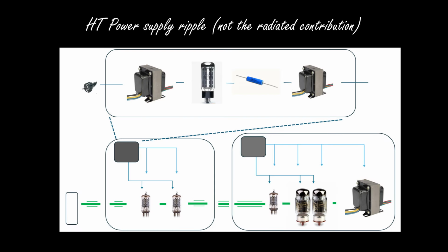Of course, preamplifier tubes are the most sensitive in that regard, so it's very important to provide a very clean anode voltage to the preamplifier tubes.